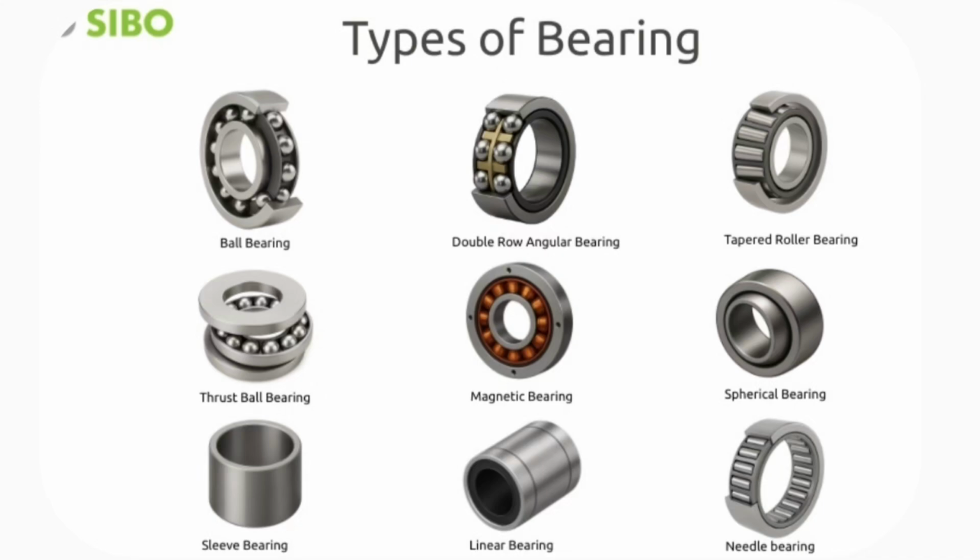Cylindrical roller bearings: high radial load capacity at high speeds, commonly used in electric motors and gearboxes. Tapered roller bearings: conical rollers that handle simultaneous heavy radial and axial loads, e.g., car wheel hubs and differentials. Needle roller bearings feature thin, long cylindrical rollers. Ideal for tight, compact spaces where radial space is limited, e.g., transmissions and engine rocker arms.